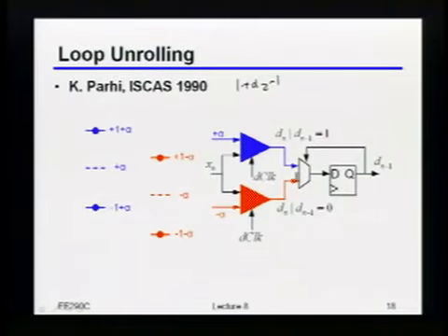Okay, so again, just like with a normal DFE, this is completely recursive, right? Because notice I need to know what the previous bit was to select the current correct bit. But that's no different than what we were doing in the analog domain as well. Okay? So the trick here is that now I've removed the analog settling time from the picture because I'm just statically selecting between these 2 coefficients that I'm going to set. Okay? So now I've pushed the timing path to be purely this digital loop that may actually be much easier for me to get closed. Okay? Does this make sense to people?